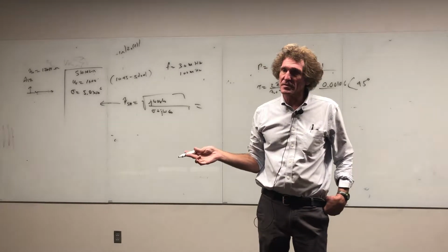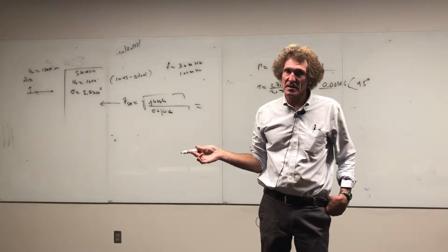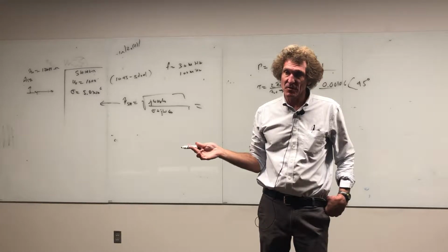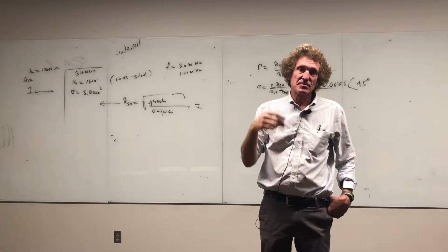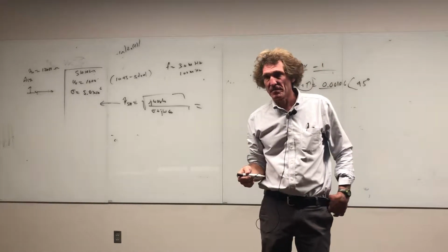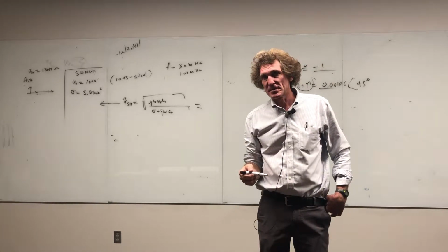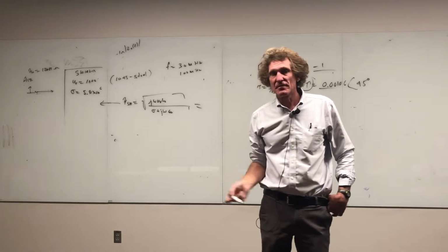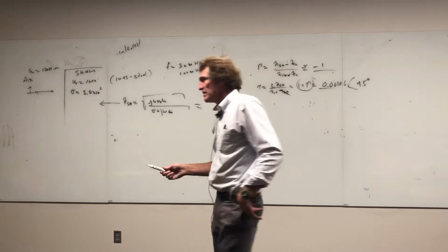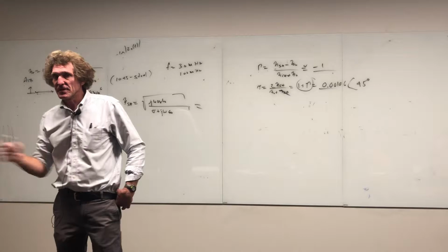These are straightforward things. They're not hard to do, but you have to do the calculations right for the eta values. That's the whole thing. The reason I introduced this is that 1045 steel is common. There's a couple of types of steel. The value of mu relative is a function of frequency, and conductivity to some extent is a function of frequency.